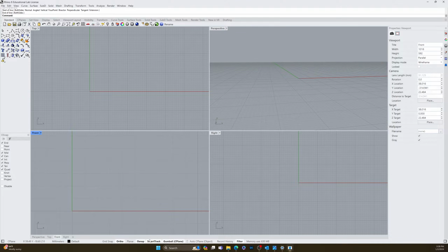I'm going to go through all of this with PC, and then I'll show you the Mac version in a minute. Most of this is going to be on the screen, but it's just not in the same spot for some wonderful reason. Smart Track basically allows you to line up objects based off of other objects. I'll get into what I'm doing on the screen in a minute, but if I have Smart Track turned on and I want to draw another rectangle right next to that, I go rectangle and then grab on, don't click, but just hover and then move, and you see that line that comes up. That's Smart Track. I can come down here before clicking and do it down here too. So it tracks the line. That's Smart Track.